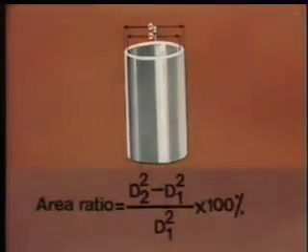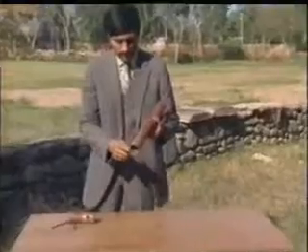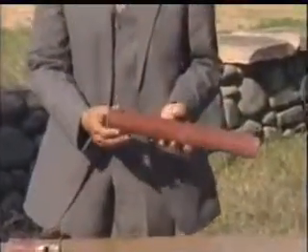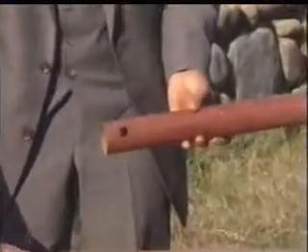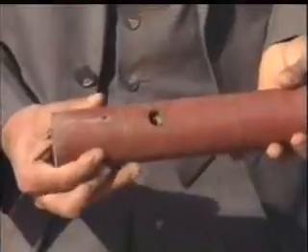Thick-walled samplers are those having area ratio greater than 10 to 25%. An open drive sampler is one such sampler. It consists of a tube open at the lower end and attached to a head at the other end.